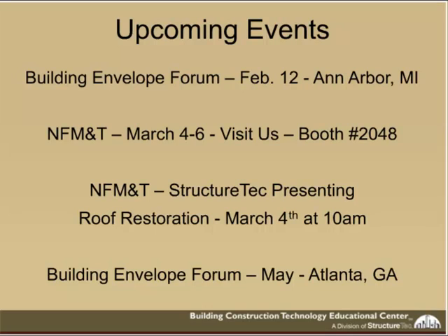Good question for me that I know I can answer here. You discussed at the start of the presentation that EIFS looks like concrete. How, again, can we tell the difference between EIFS and concrete? I think the easiest way, at least the easiest way that I found, is going outside to the exterior, taking your key out of your pocket and just giving it a couple quick taps. You'll notice it's hollow, and you'll be able to tell. If it's solid, it's concrete. If it's hollow, sounds kind of like a drum, that's EIFS.